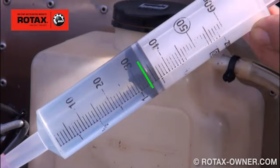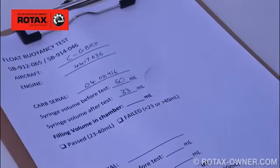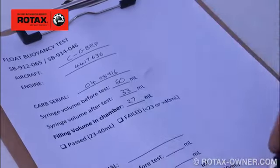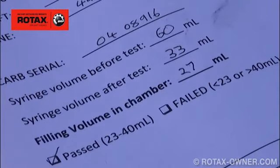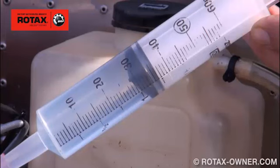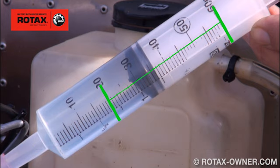Record the volume of fuel remaining in the syringe. Subtract the second syringe volume measurement from the starting syringe volume measurement to arrive at the float chamber filling volume. If the amount is between 23 milliliters and 40 milliliters, the floats are okay. The float level is within the limit.